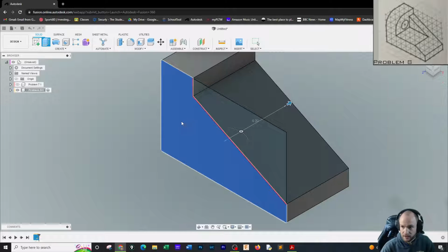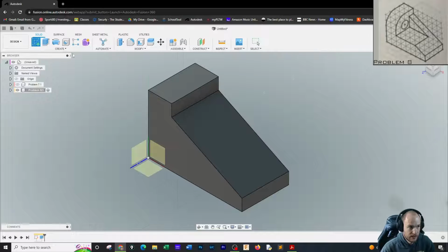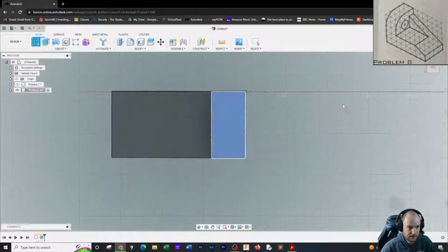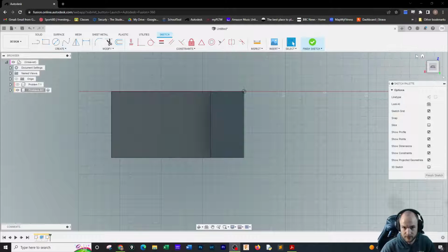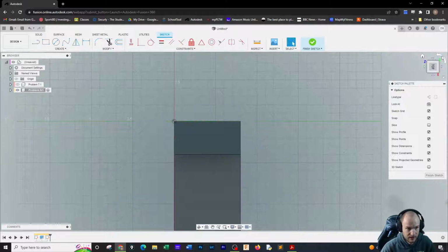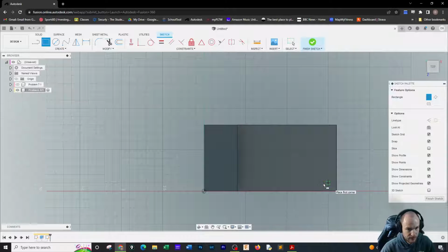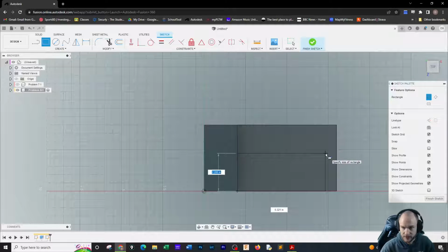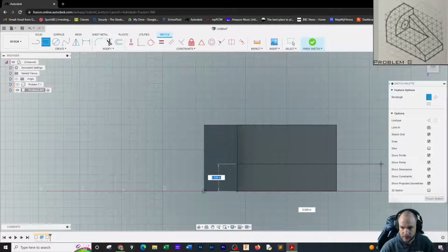And then I'm going to have to do some tricky stuff here. Okay, so I've got to make from this top face, I'm going to rotate it quick. I think this is the simplest way to go about this. I got to make a sketch here. For this area right here, I want to cut down. Now, since I can actually grab onto this edge, I don't have to project the geometry. But I do want to turn my drawing back on so I can see what I'm looking at. Okay.